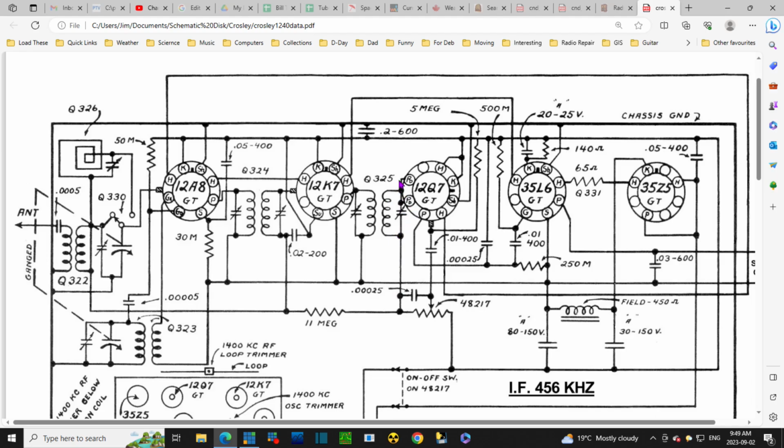And if the diodes are turned the right way, you can get a negative voltage building up here. Now, you could throw it away or ignore it or pay no attention to it. But as it turns out, there's a trick that can be played with this voltage. So here it's sent in two directions, isn't it? It's going this way through this volume control, which is probably 500,000 ohms, something like that. You can go this way, it goes through an 11 megohm resistor.